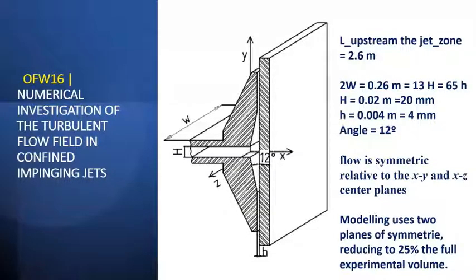This is the geometry of this internal flow, and the main dimensions. The modeling work was performed using two symmetry planes, which reduces the geometry modeled to 25%.